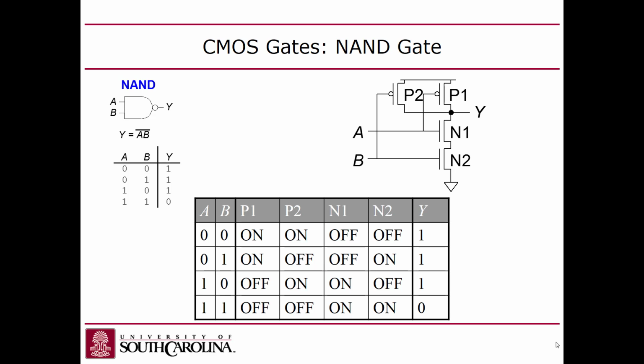And it has to do with the fact that the gate voltage is actually relative to the source terminal. So you need to have the NMOSs, their gate voltage has to be relative to ground. So you have to put those on the ground side. And the PMOSs have a negative threshold that turns them on, so they have to be up here by VDD. That's kind of the simplified explanation of it, right? Makes sense?